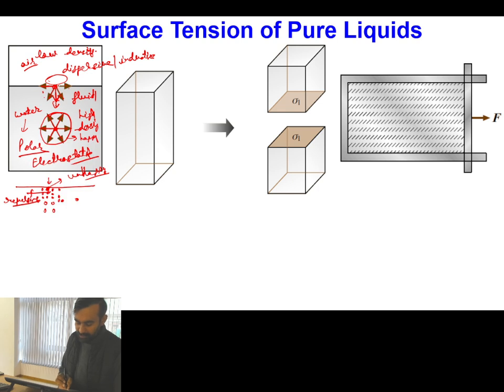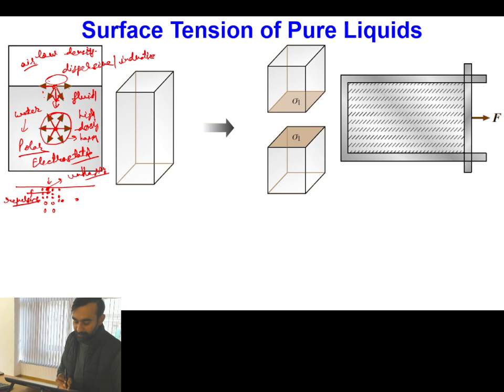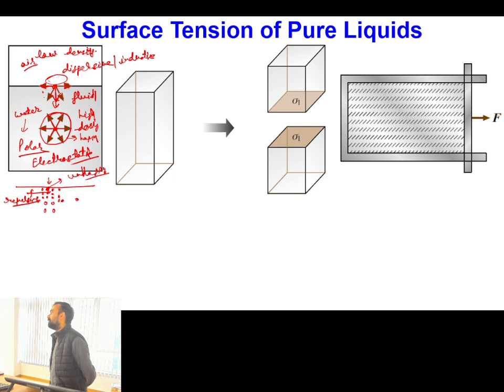But molecules which are close to the interface, free surface, these typically try to come towards the downward direction and this downward motion is actually balanced by the repulsive forces which are generated because of the intermolecular distance, and ultimately these molecules have to stay over here. But whenever this molecule is staying over here, this molecule is also receiving some tension force along the interface. So it means it is always in the state of unhappy.